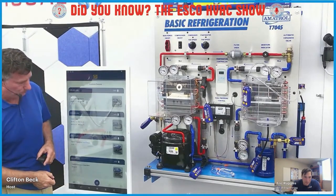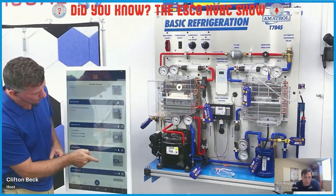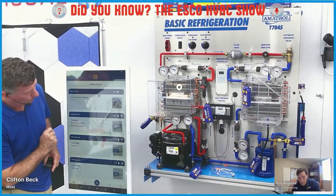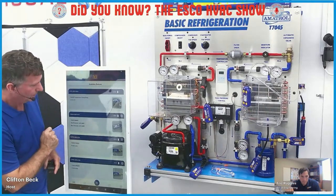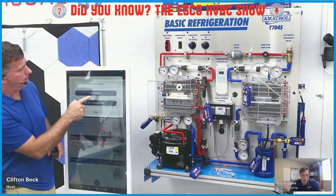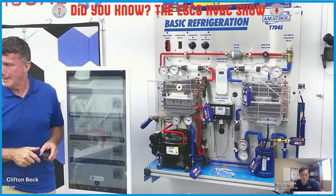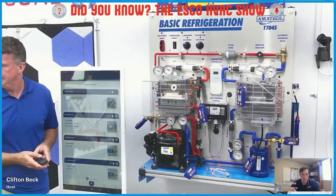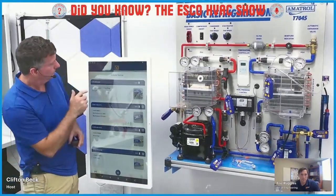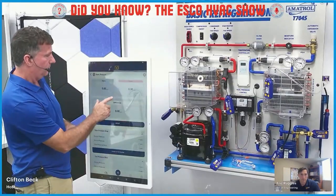Okay. Find your manometer. Scroll down to find your manometer. And there's a little gear key on the right side of that blue bar at the top of the manometer. Step back for a minute. Little gear logo. Yep. Click on that. And then it allows zero pressures. Perfect. You should be able to go back to that session, and it should be zeroed out. Okay. Cool.